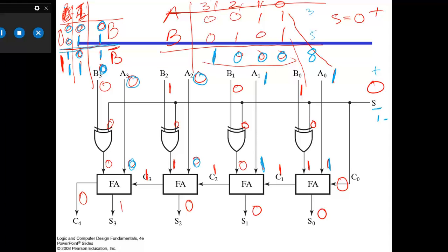So you can see if you take one bit as C and one bit as I, when the C bit is 0, whatever is at the I is at the output. I is following the B, and if this C is 1, whatever is at the input, the complement is at the output. So this complement is basically 1's complement. If your XOR gate is in this mode, it will give you a 1's complement answer. So let's solve this with examples.